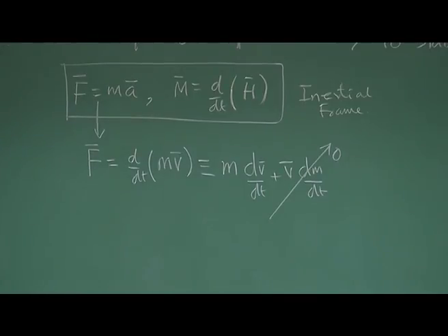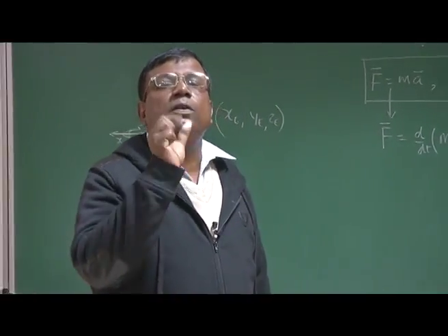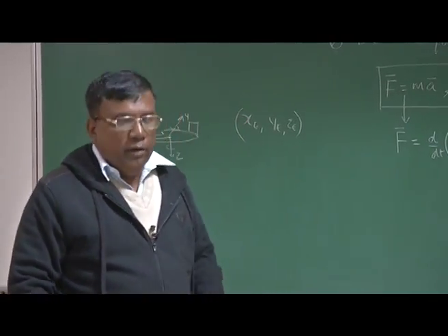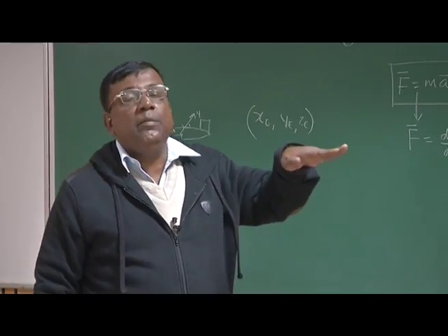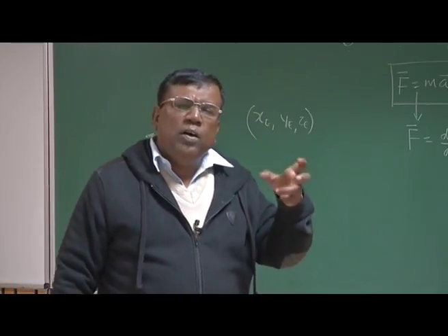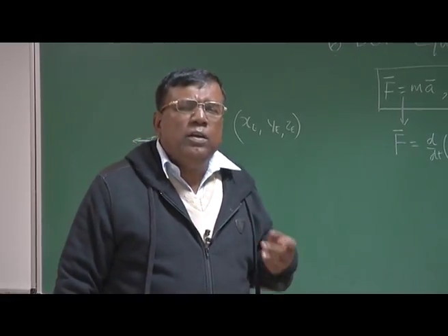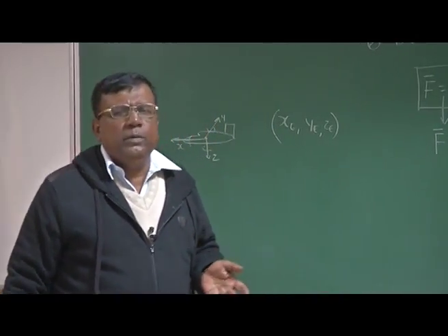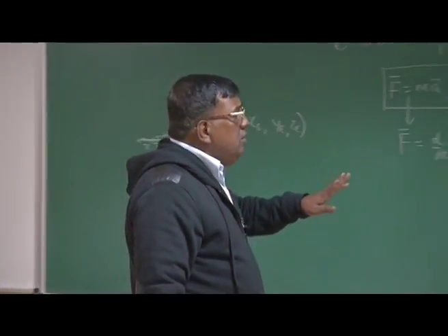We are doing a stability analysis. Our aim is to do dynamic stability analysis, so we will be studying the response of an airplane for a short duration. For example, it is in the cruise. Now we give some deflection and see what is happening. But this study will be for a very short duration with respect to the trim condition. And during that short duration, it is fair enough to assume that the fuel consumption is negligible. So this assumption is okay.